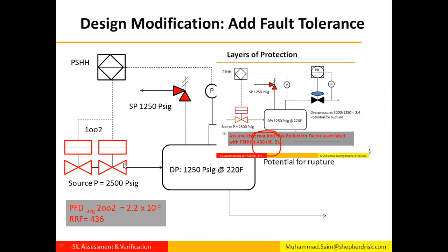So there's one point here to remember. Let's assume our PFD calculations tell us that the one ESD configuration can give us the desired 400 risk reduction. Let's assume it. So we will say, okay, with the PFD calculations, we can get the RRF of 400 with 1 ESD valve, so we'll provide only 1.